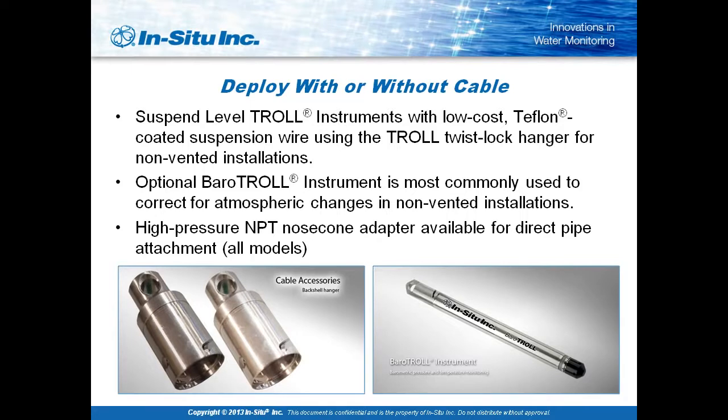You should use a desiccant or a cap on the cables and on the instrument itself when they're in storage, because even in the standard atmosphere, you can eventually pick up enough moisture to compromise the instrument. A non-vented or absolute instrument, since it is not open to the atmosphere, doesn't need desiccant, so you don't have to worry about it. You can cap them up without any problem.